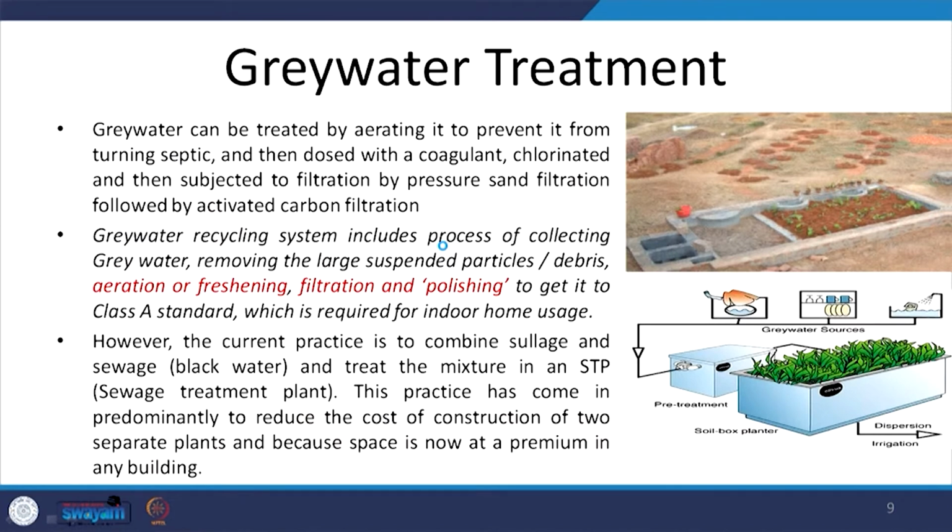Now, when we are talking about the grey water coming from a household, it is a combination of all these three. If required to optimize the cost, one type of the grey water might be left out. For example, grey water coming from cloth washing, which is very heavily polluted with chemical contaminants, may be left out of treatment.